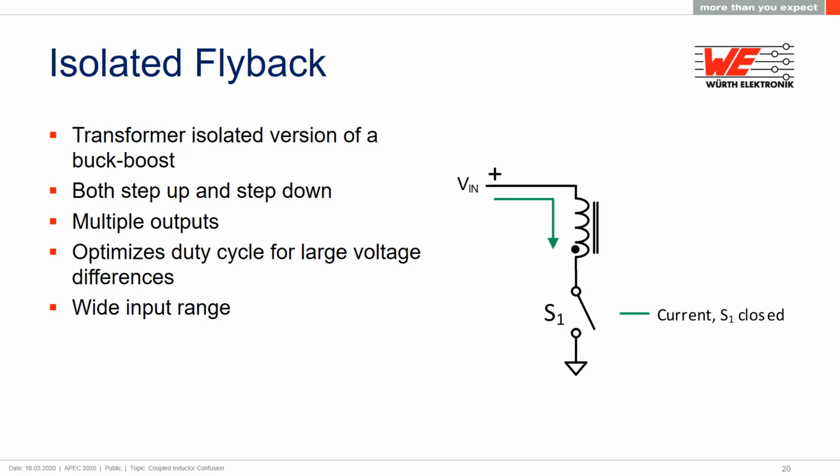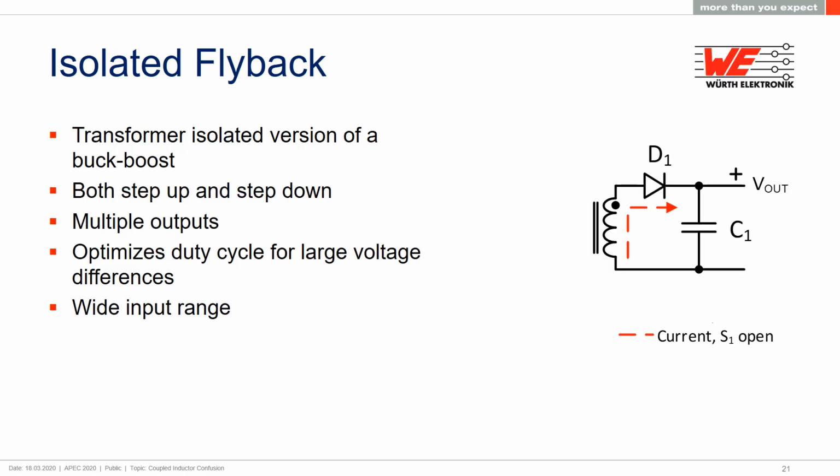When the switch opens, the current wants to continue flowing. The collapsing magnetic field reverses the voltage polarity, which rises until something happens. The energy has to go somewhere. It turns out in a flyback, because the windings are linked by the core, both windings have the same action. The output winding conveniently has this diode oriented such that now that the winding voltage polarity has reversed, it can conduct and current will flow to the output capacitor and load. The stored energy is harvested for the load.